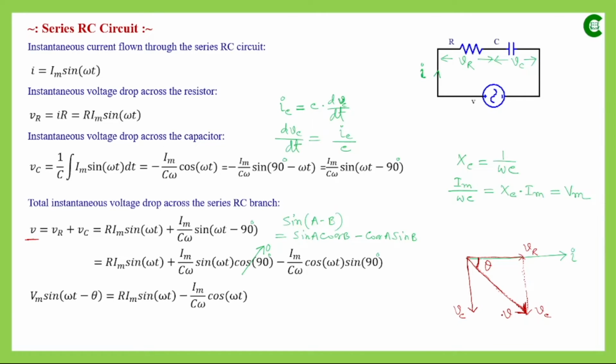Since we have a capacitor, it will follow the nature of the capacitive circuit. So here also the voltage drop will lag the corresponding current, but this time since it is not a purely capacitive circuit, the phase difference will be no more 90 degrees, rather it will be less than 90 degrees.